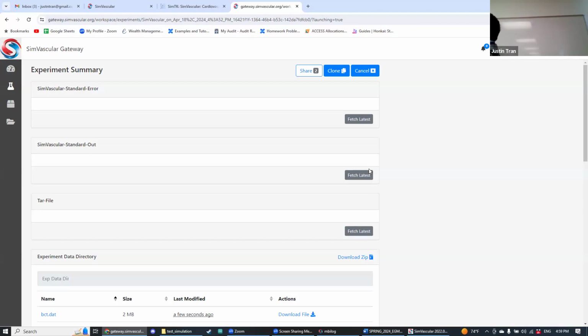It seems like when I ran the smoother on it, it fixed a lot. Okay, good. I'd probably fix some of those segments a little bit more. So were you able to get a mesh on it today? I didn't want to run the mesh just in case I had to change my segments. If you're able to get a mesh with a reasonable amount of elements, I'd say that's okay. But if you're having trouble with the mesh, then I would go back and revise. Thank you.